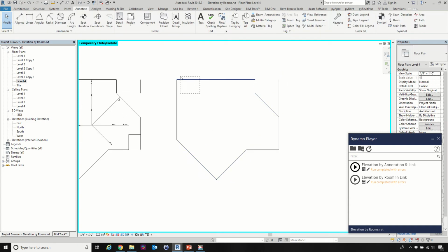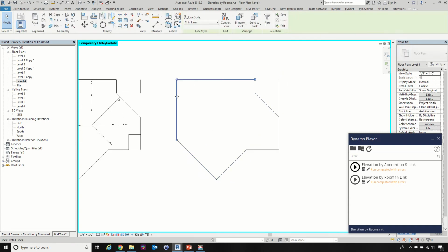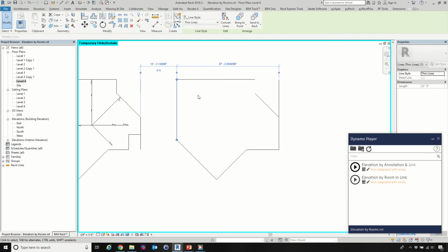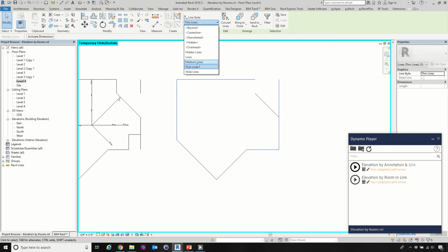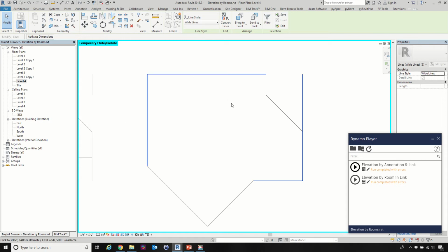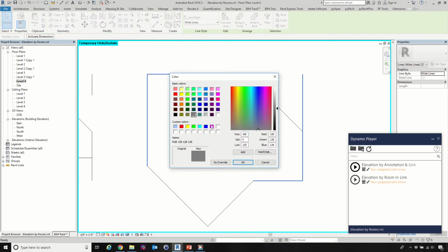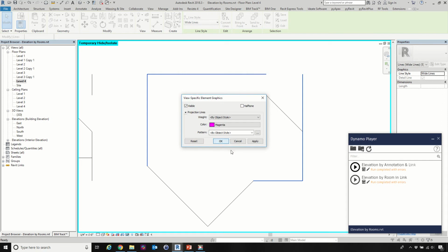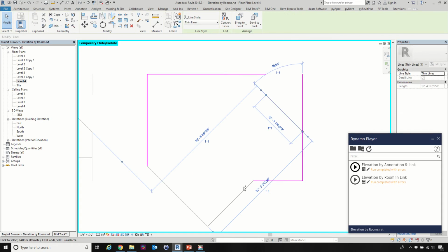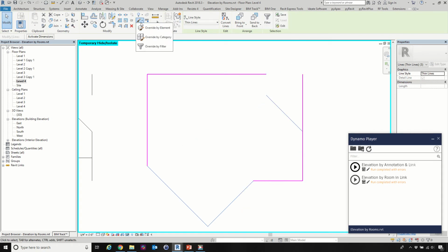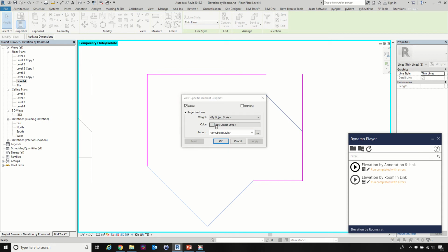Now group them by perpendicularity. So we take one of the curves, we take one of the lines or curves, and get all the other curves which are perpendicular to them. So these 4 lines will belong to one elevation marker, and the other 3 lines belong to the other elevation marker.